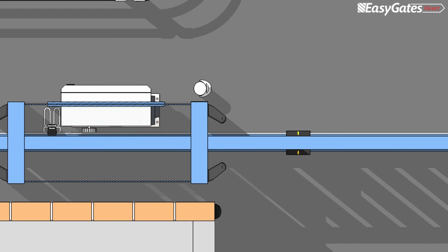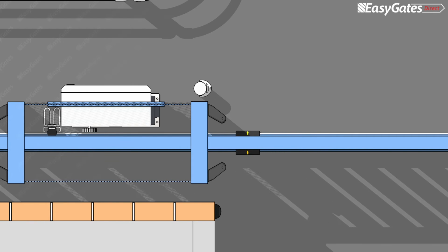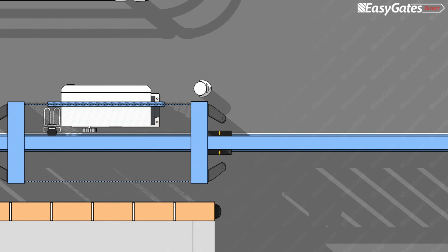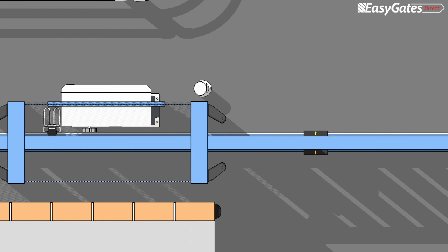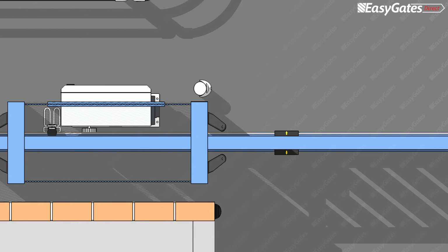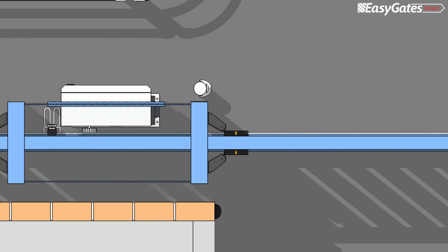Once in place, carefully push the sliding gate leaf toward the portal edges to ensure the test piece is detected. Ensure that the test piece is detected on both sides of the gate portals. If the test piece fails to activate the safety edges, then this is considered a fail, and further preventative steps must be taken to address this hazard. For example, the edges may need to be moved further in or changed for a different type and depth of profile. Repeat the tests for any further portals or positions relevant on the gate.